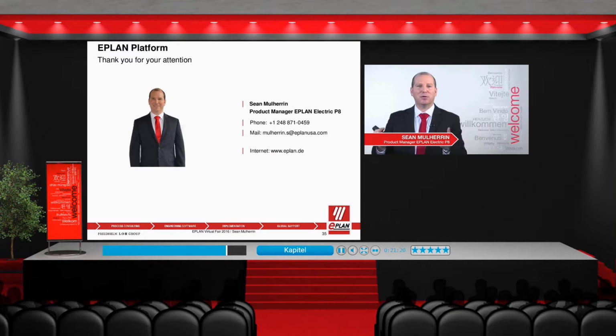So we had a couple of questions during the presentation, and I will talk about them. So first of all, from Romania: Is it possible to finalize a PPE project without using any instrument parts from the EPLAN database? Yes, it is. PPE is for plant process engineering. It's our tool to do our process flow diagrams or our process and instrumentation diagrams. So yes, you can complete a P&ID, you can also complete your data structure, and you can finalize that project without necessarily using the detailed engineering required for that.